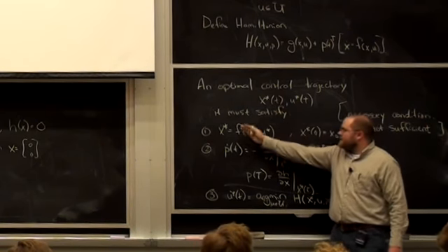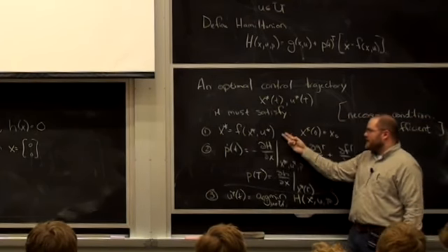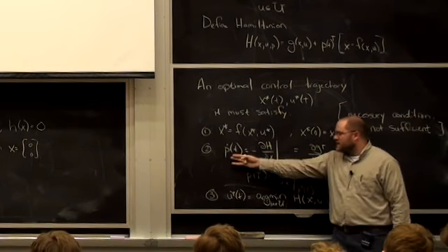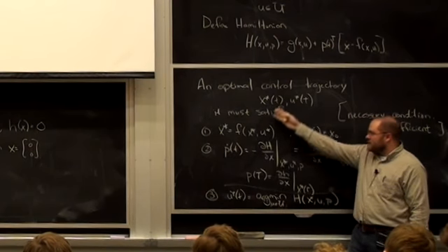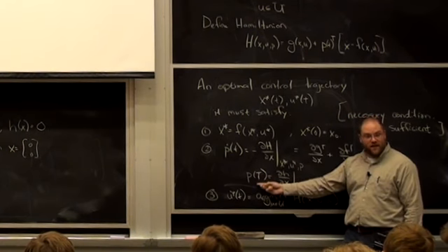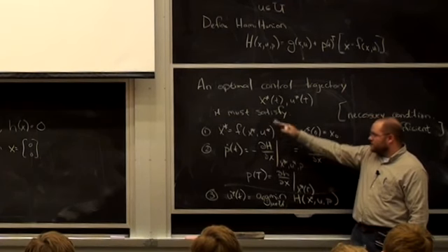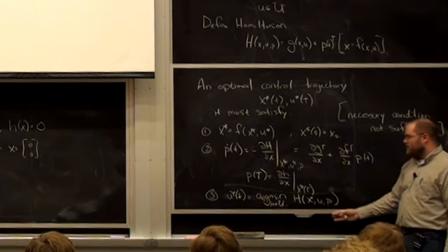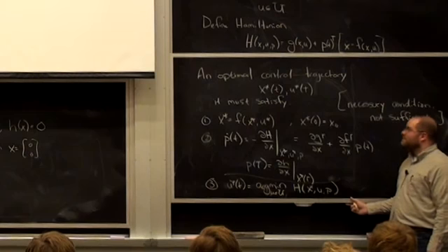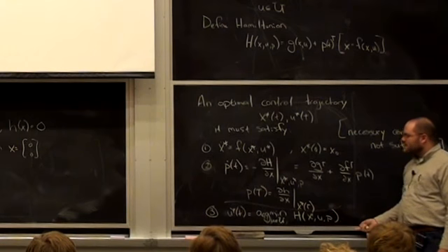It says that if I take my x and I integrate it forward in time, solving for x by integrating my dynamics forward, and then I take this other new set of variables, p, which happens to have the same size as x, we'll see that, and integrate it effectively backwards in time because I have a final condition on p. If I do both of those things, and I can write down u as being the argmin of H, then I've satisfied a necessary condition for optimality. Okay, let's try to make sense of that.